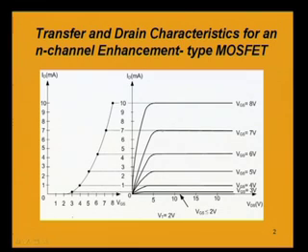So, in this plot we are drawing the transfer characteristic by extending the saturated current and finding out the intersecting point between these values of the saturation current with the corresponding gate to source voltage.